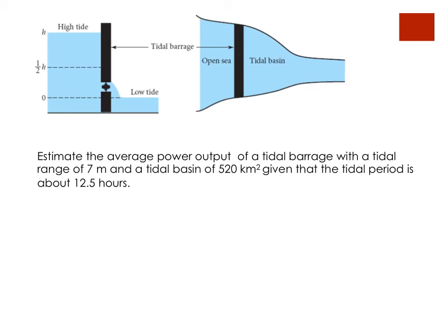First, let's think about the gravitational potential energy of the water that's behind the dam. It will be 1/2 mgh, as 1/2 h will be the average height of the water. And energy divided by time is power, so the power we will get will be mgh over 2t. In order for our answer to be in watts, that time does need to be in seconds, not hours.